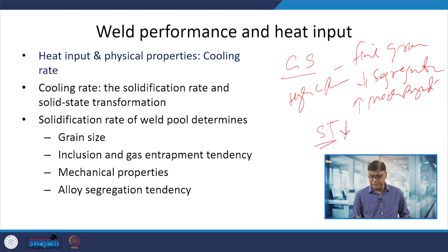So, these are the three favorable things which will be realized, but when the cooling rate is high, our solidification time is very less. So, when the solidification time is less, then there is a tendency of the entrapment of the gases, entrapment of the inclusions. So, there is a possibility that the inclusions and the porosity formation tendency is increased. If the cooling rate is slow, then the things will be rejected slowly, the gases will have enough time, inclusions will have enough time to come up to the surface and float over the surface. But that does not happen in welding, because the solidification time is usually very low.